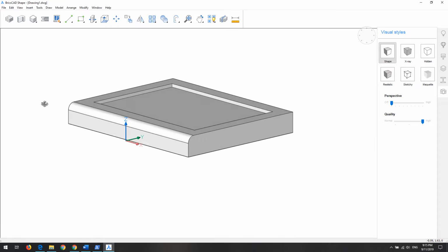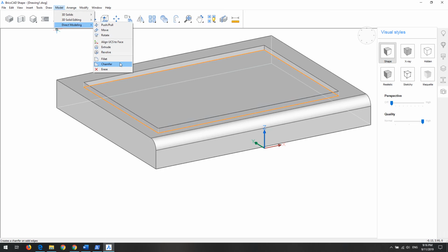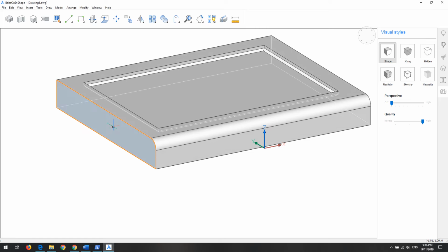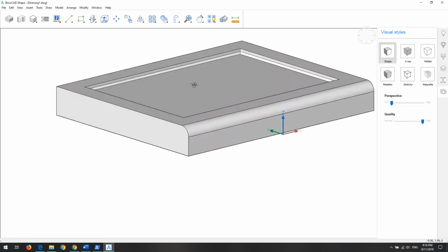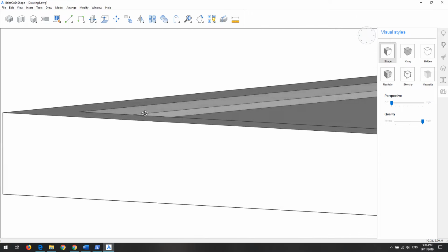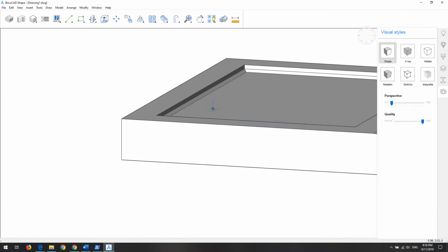Seems like it didn't work. Let's try again. Let's select the boundary, and let's type it in. Sometimes you have to type it in, because the mouse is, let's say, imprecise. 0.02. Now it worked. So we just applied a chamfer, or bevel. In Blender it's called bevel, on this particular edge.